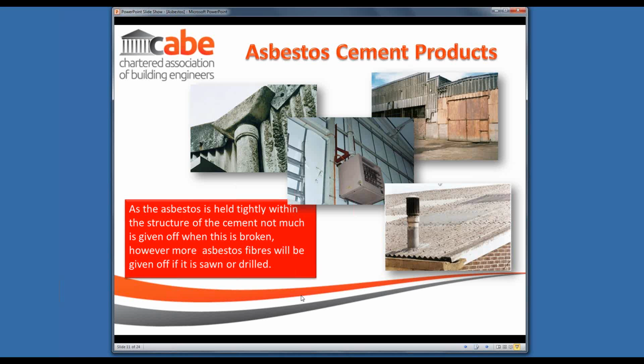You can quite often have situations where people have identified asbestos within the premises, and that asbestos has been sealed to ensure that no fibres can then come off it. This is quite often the case if you've had an old boiler that may have had an asbestos flue. The boiler's been removed, but somebody doesn't want to take the flue out throughout the property, so it will be effectively sealed and the actual material coated and sealed to prevent fibres being given off.